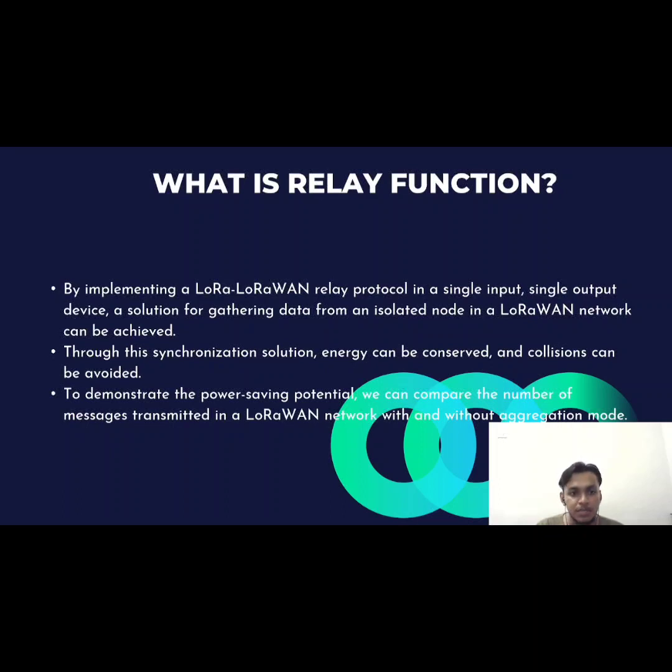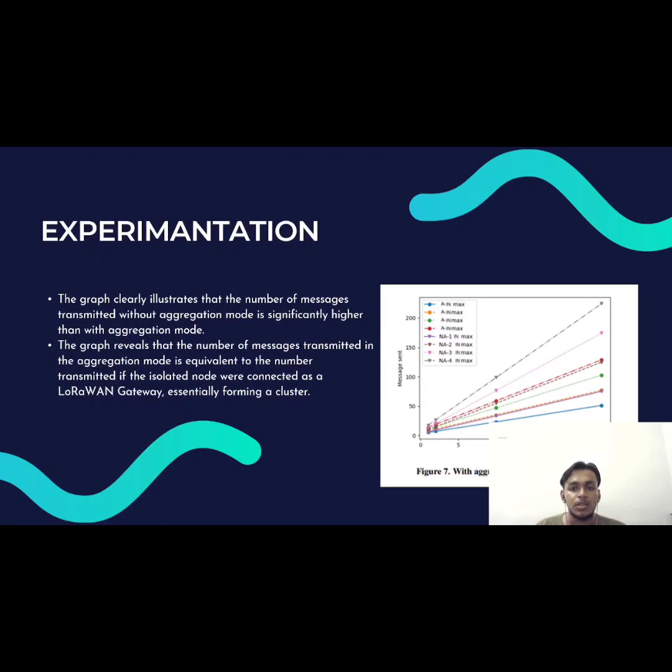For the power consumption part, we have done research on the relay function, which is the usage of aggregation mode, in order to see the difference in power saving potential between the LoRa and LoRaWAN protocols. These are the experiments that have been done. This graph clearly illustrates that the number of messages transmitted without aggregation mode is significantly higher than with aggregation mode. The graph revealed that the number of messages transmitted in aggregation mode is equivalent to the number transmitted if the isolated node were connected as a LoRaWAN gateway, essentially forming a cluster.